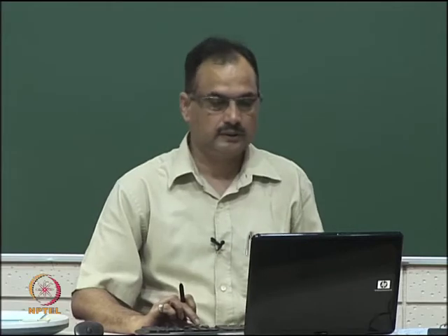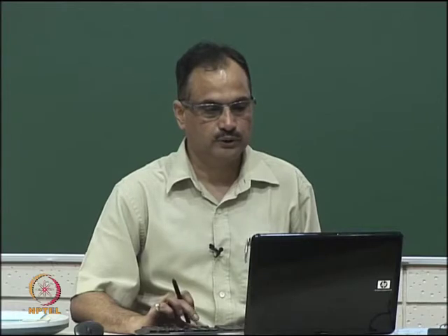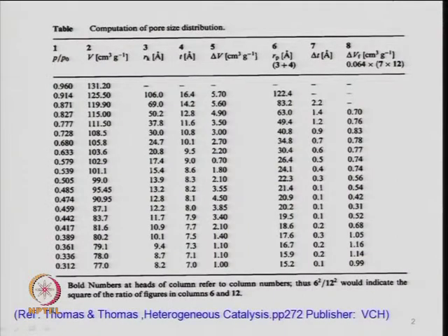In the last lecture, I was talking about pore size distribution and I discussed the algorithm for the evaluation of the properties or thickness of the pore, rather the adsorbed layer thickness, and the pore size distribution, which was a cumulative pore size distribution or the change in pore radius as a function of pressure.